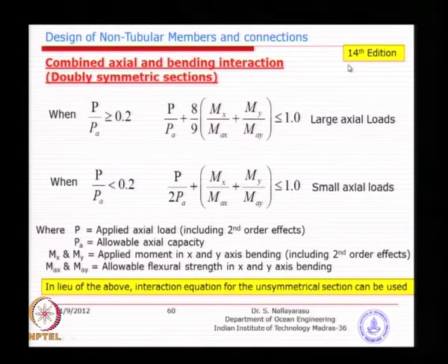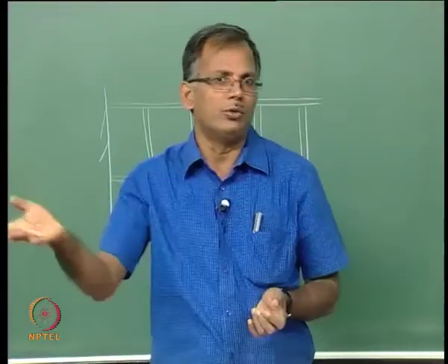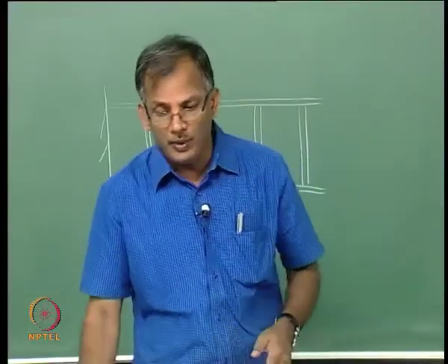So, if you use methods 1 and 3, not the effective length method, then you will be using the moments modified by these effects. That means, already incorporating those two effects, the moments and the axial forces are recalculated. I think yesterday we spent some time looking at the moment obtained from first order multiplied by beta 1 and beta 2, you get a value which incorporates those effects.